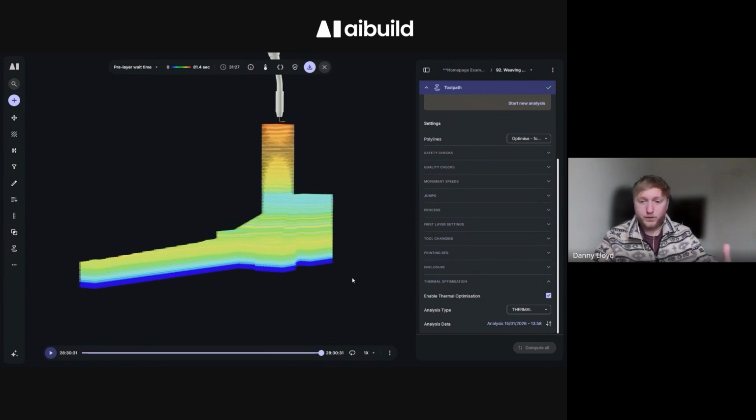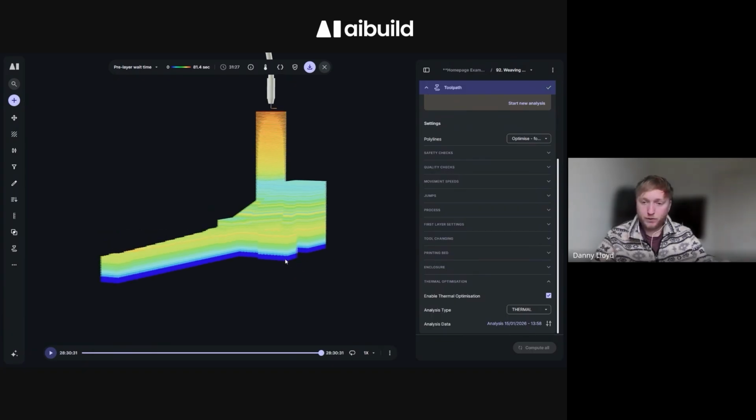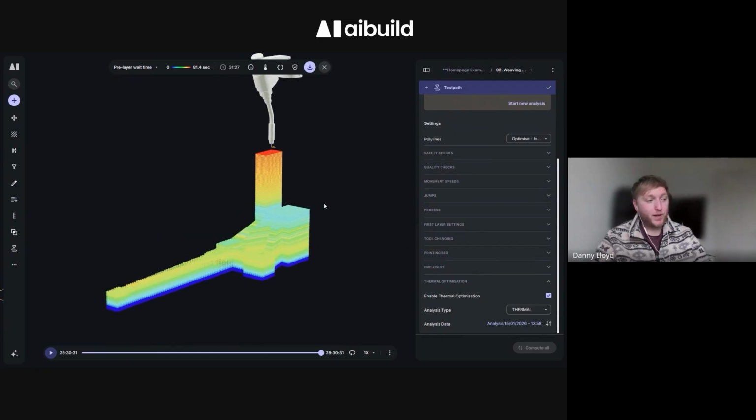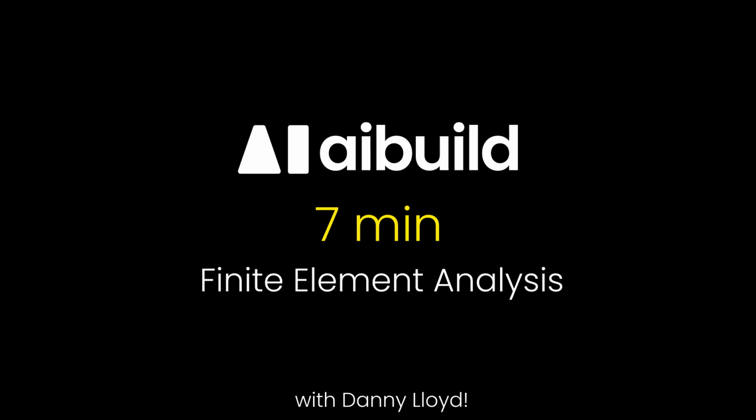You see now every single layer has been given its own interlayer dwell period. So you can see for the first few layers, there's no pausing necessary, but then the heat starts to build up. It goes above our maximum threshold temperature. You get accurate production time estimations as well, because the printing without the pausing, just straight printing, is about 15 hours. When you add the pauses in between the layers, we've nearly doubled the print time. So that's important for production planning and time estimation.